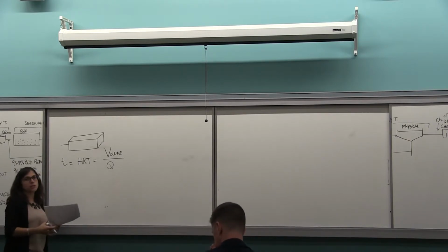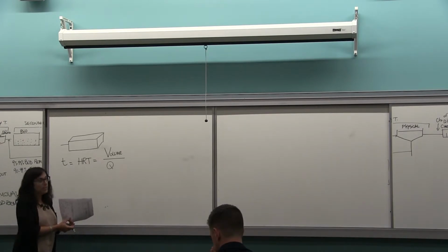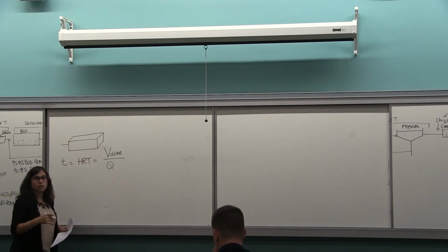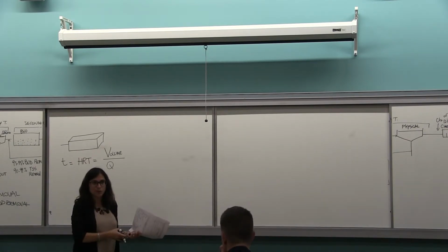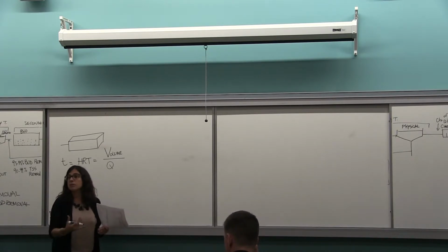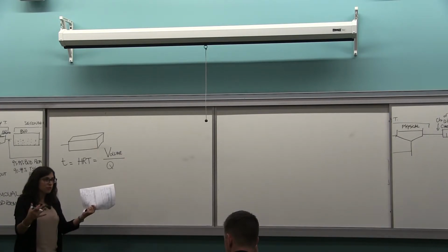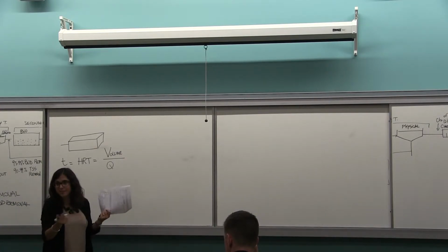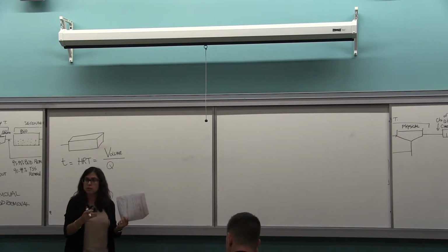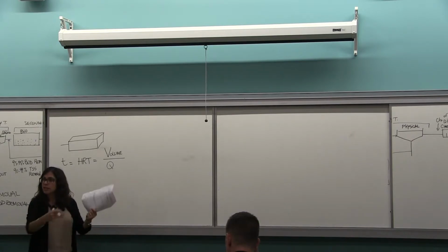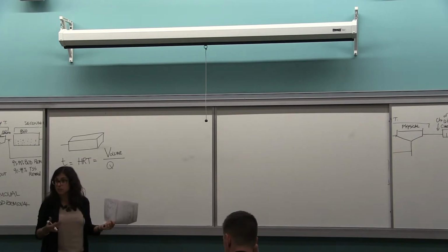That's the time that the average water spent in that tank. But this is if it was a perfect system. So this is the theoretical residence time. In reality, because of the shape, you could have some water spent there 2 hours, some 1.5 hours. So there is what we call efficiency of the clarifier. If we design perfectly, it would be 1 or 100%, but the efficiency usually is less because you're short circuiting, and depending on if it's elongated, it depends on different factors. And usually we do a trace analysis to determine what the efficiency is.